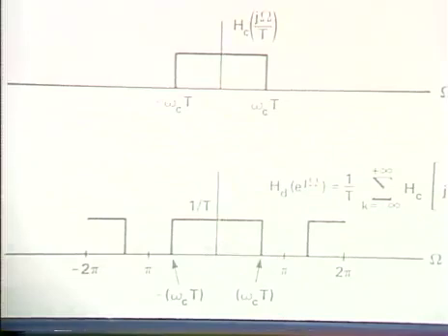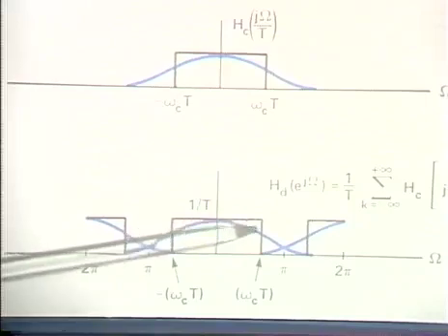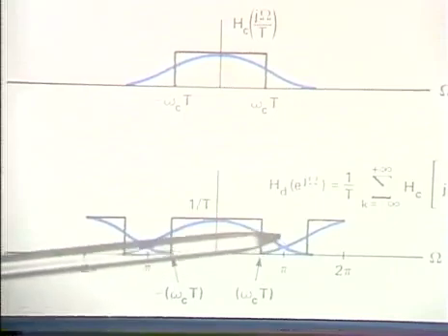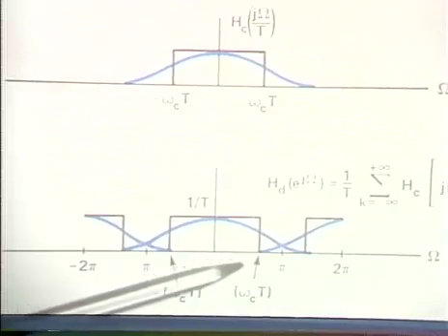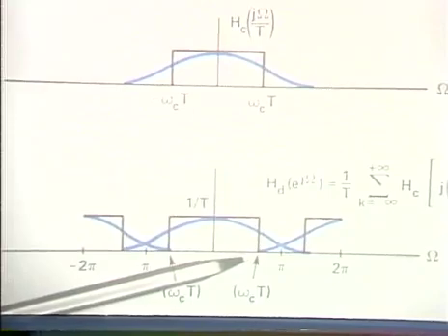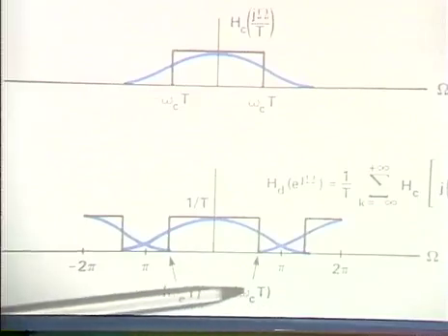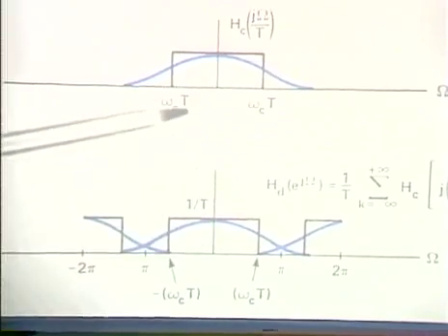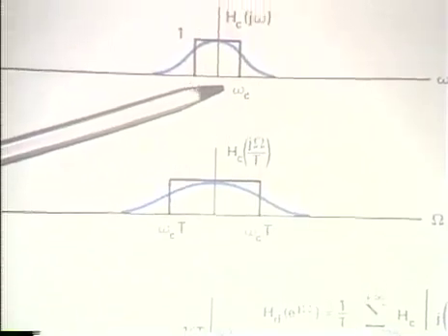Of course, since this isn't an ideal filter, it has some transition from pass band to stop band, and as we discussed last time, there is aliasing, which we need to at least be aware of. We've specified certain frequencies along this axis which are easily related back to the continuous time frequency axis through this mapping, as we have here.